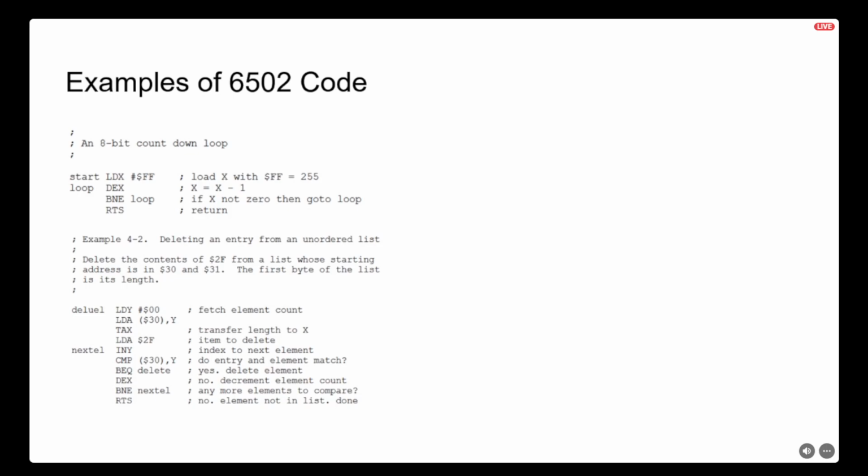The processor is able to recognize binary and decimal and hex as the same value. Hex is standard. It's the most concise. Just be consistent with it. Don't go using different bases just because you can. So with the 6502, bytes go from 0 to 255. So that's what we are loading into the X register here. And hex numbers in assembly are prefixed with this $ sign. That just tells the processor that this is a hex number, not an address.